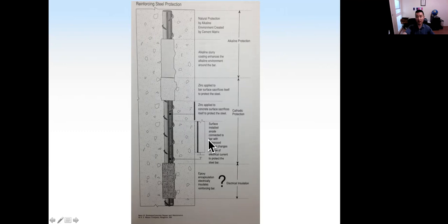So when we talk about corrosion of reinforced concrete, we talk about the half cell potential. The chemical reaction occurs in the anode and the cathode areas. So using the battery, we can reverse the flow of the current, so we can reduce the corrosion. Also epoxy: when we use epoxy, remember it needs to cover the whole length of the rebar, which is not easy to achieve sometimes.